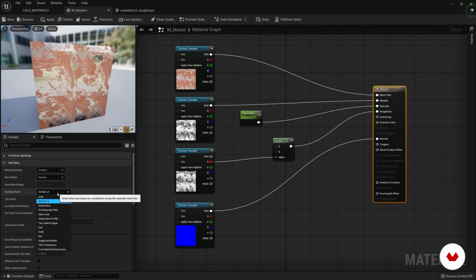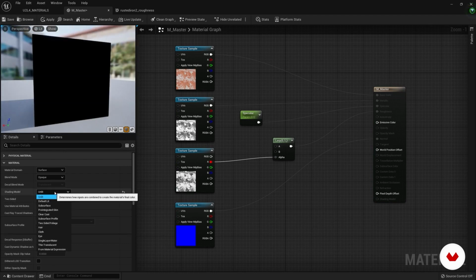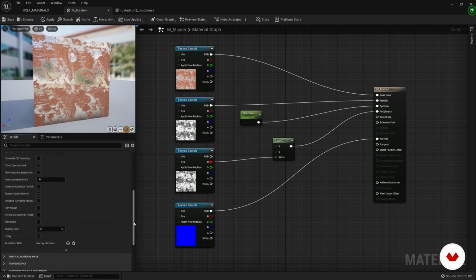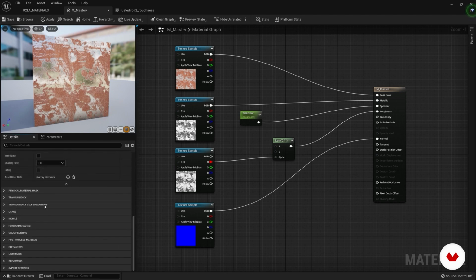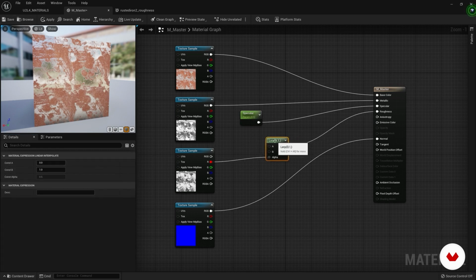Shading models are some presets that Unreal gives us to help us, like the subsurface, hair, cloth, or unlit, which is a system so the material is not affected by lights and reflections. Two-sided means that the material is visible both on the side of the normals of a polygon and on the other side. And then, gradually, many parameters, which unfortunately we cannot rattle off all in this course. What we have said already allows us to create materials.